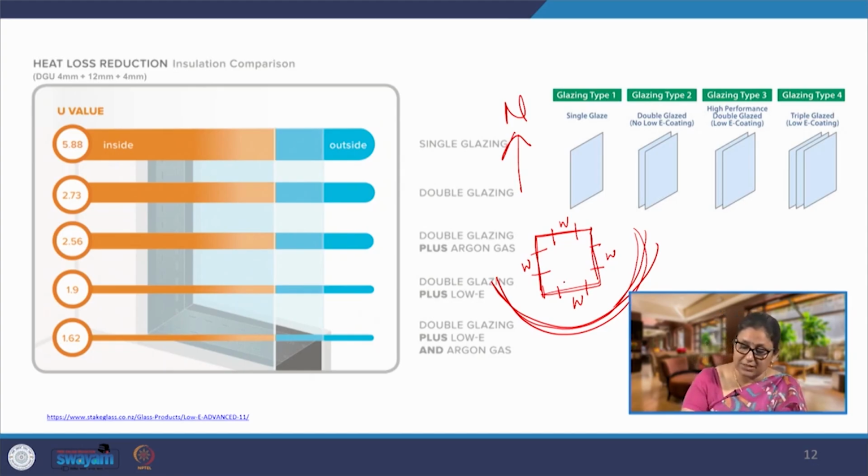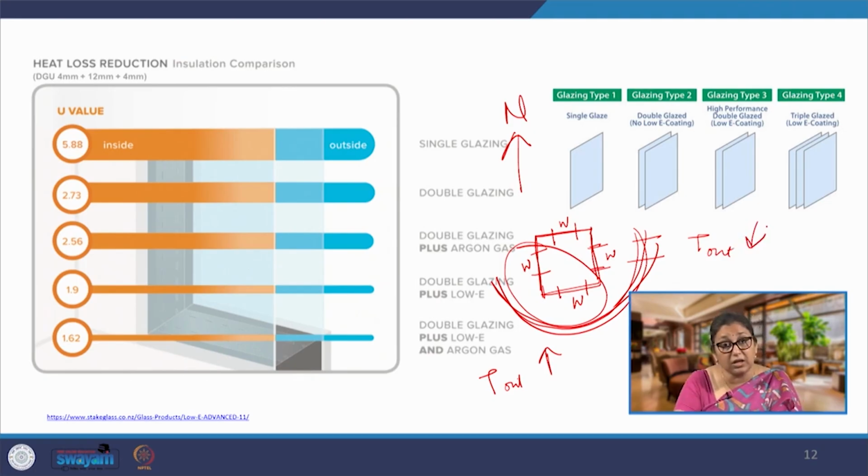When the sun is in the south and west, the outdoor temperature is going to be at its peak, plus there is also going to be radiation. When the sun is in the east, the outside temperature is going to be low, and there will be solar heat gain, there will be direct radiation. The radiation is equally intense; it is the outdoor air temperature which is changing. So, these are the 2 components we are talking about.